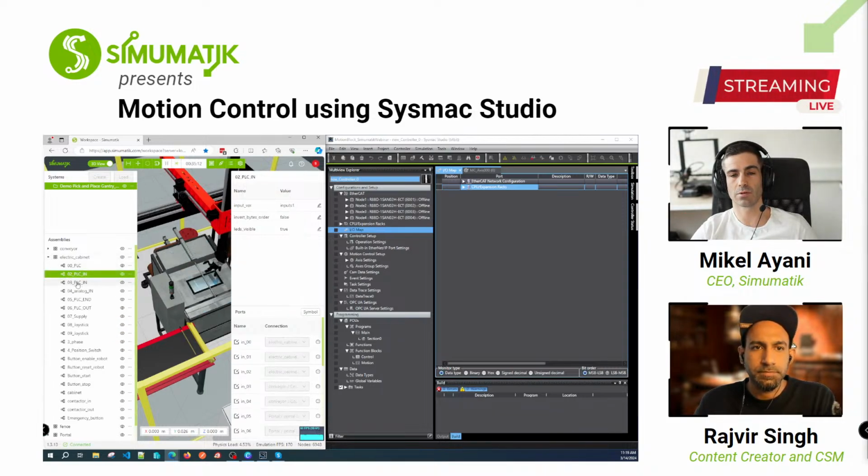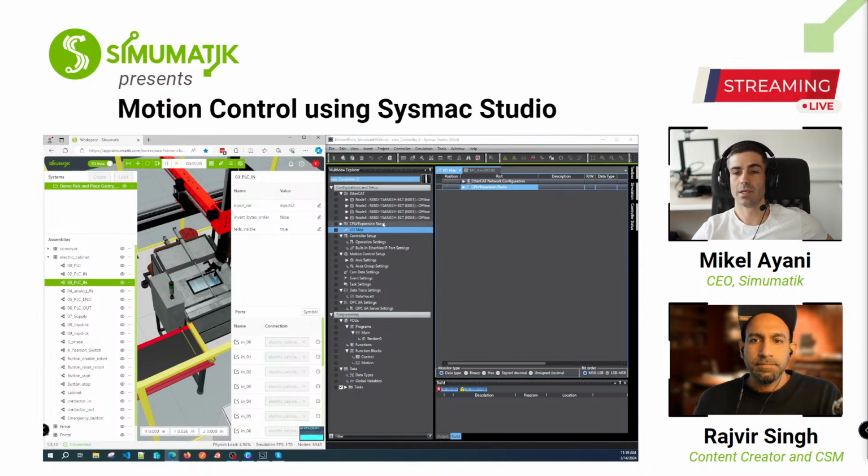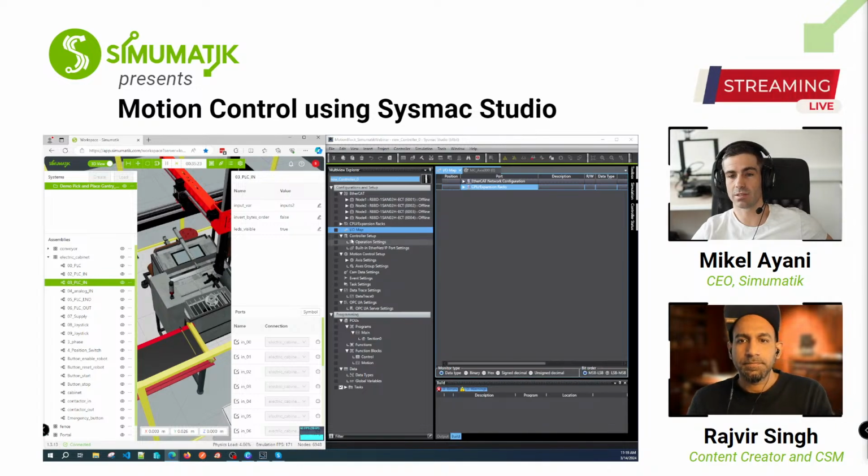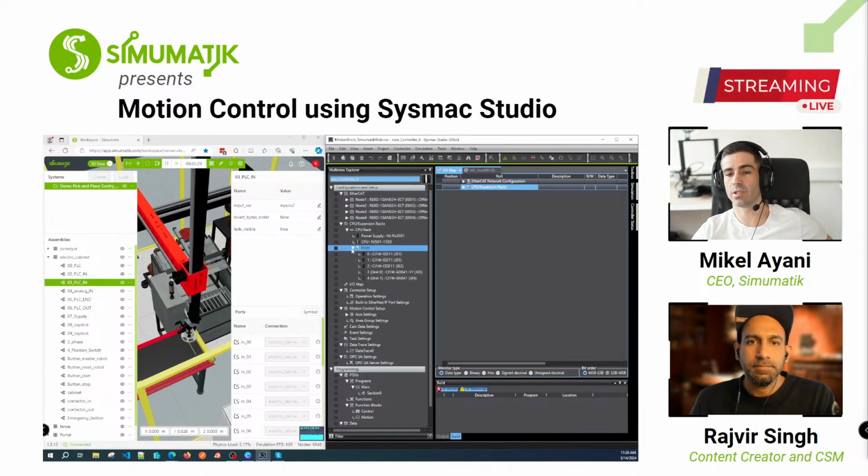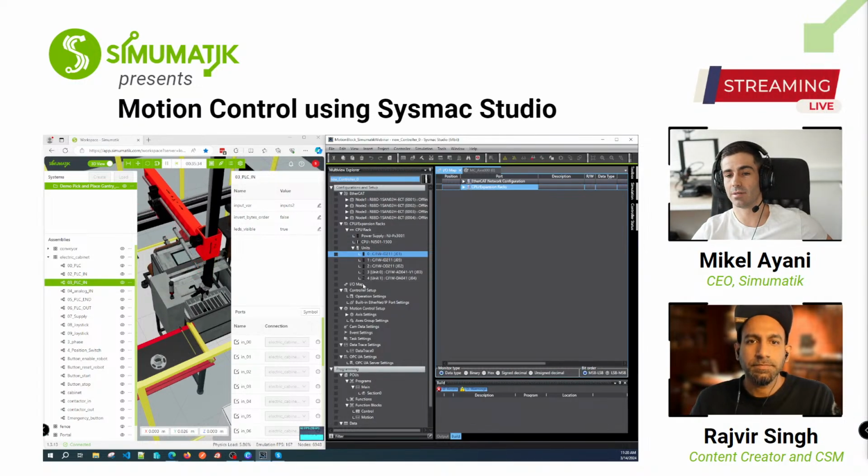So anyone that wants to reproduce what we did just builds a project in Sysmac Studio, adds the hardware, creates some global variables for the axis set points and so on, and then adds the input and output units and names them accordingly. Exactly.